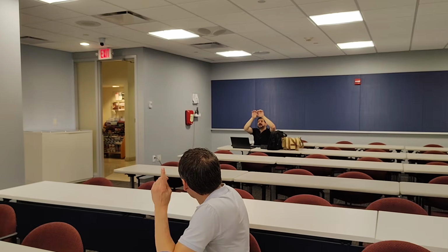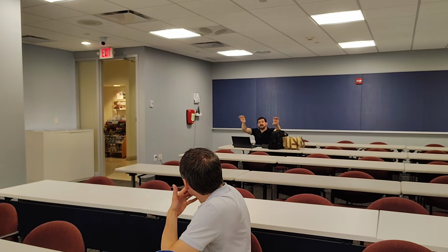You have 36 of those on that floor. You can't see them the way this system is. If we wanted to see those data points, what we would do is take those data points from the VAVs, we would mirror them in the floor level controller that we can see, on the floor, and then we could tell your BMS that information.